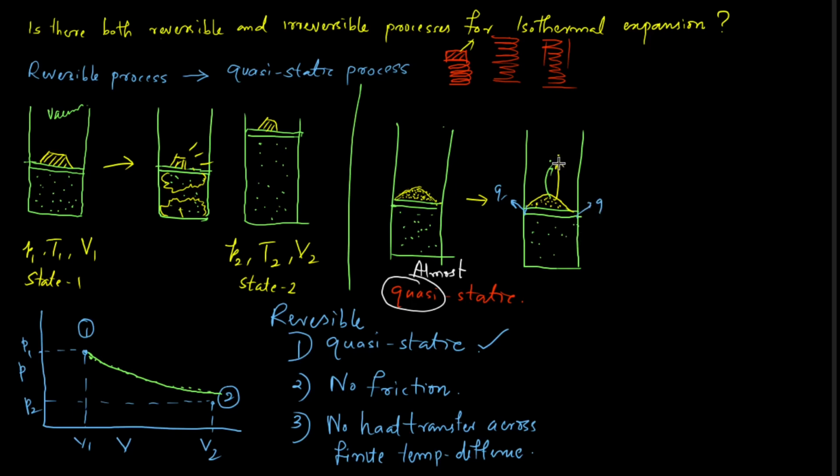So when we replace that sand particle back on the piston, this heat will not be taken back. We cannot reverse that friction; it will not take the heat back when we put the sand back onto the system. So whatever work we do against friction will always be converted to heat. We cannot recover it. So if there is friction, then the process is not reversible.